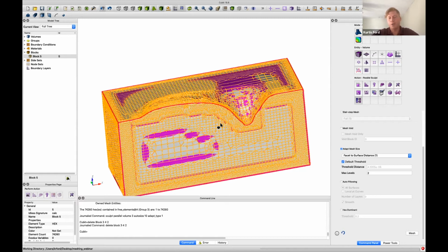And in my experience, I still find that I get better results. If I can get a high quality hex mesh, I prefer doing that because some of the stress averaging that goes into those other TET technologies can create a soft mode that is not a big deal in most cases, but in a case like additive, when it gets really hot, it can create some issues, some instabilities. So I think those will eventually be handled, but for now I use the hex mesh. So does that answer that question?